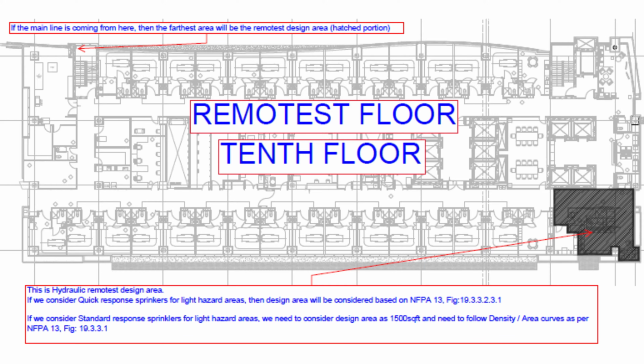In this hydraulically remotest design area, if we consider quick response sprinklers because of light hazard occupancy, then the design area will be considered based on NFPA 13 figure